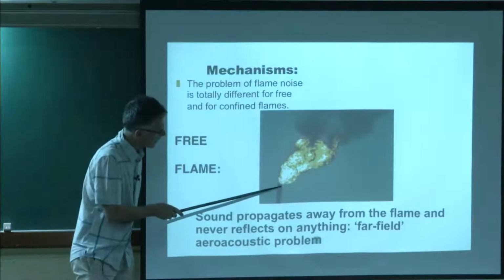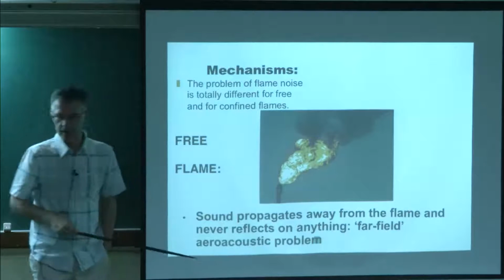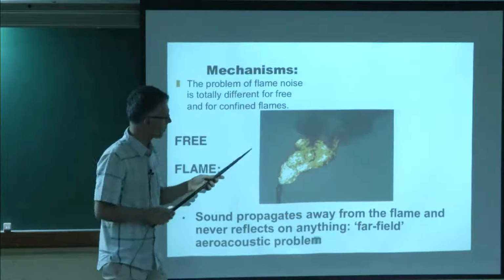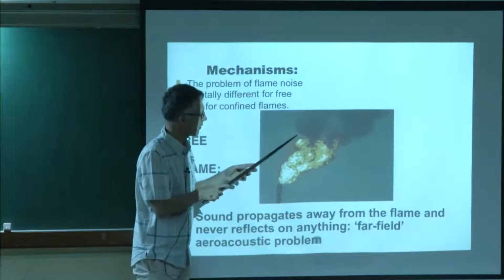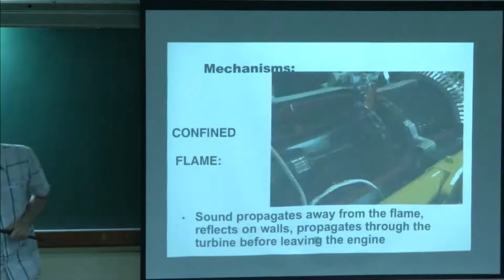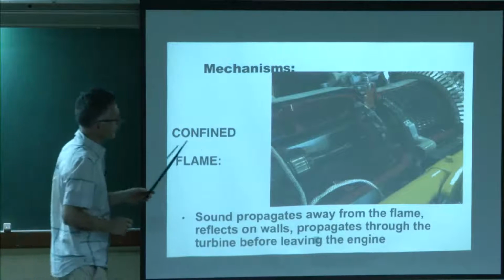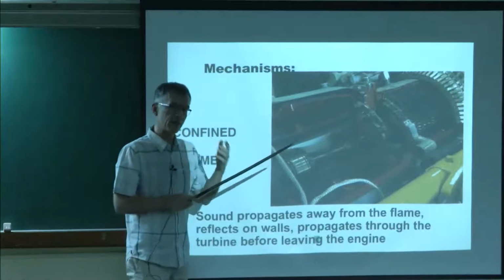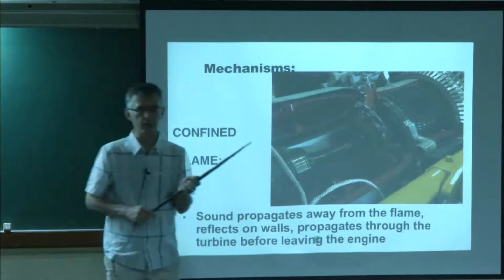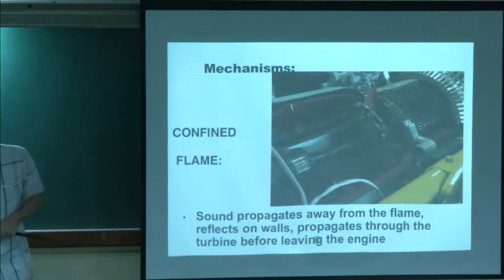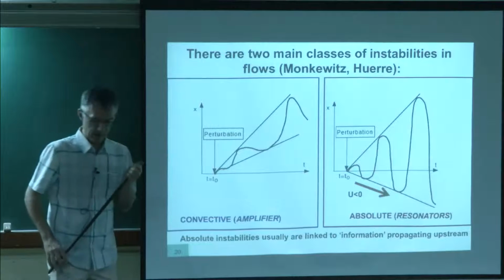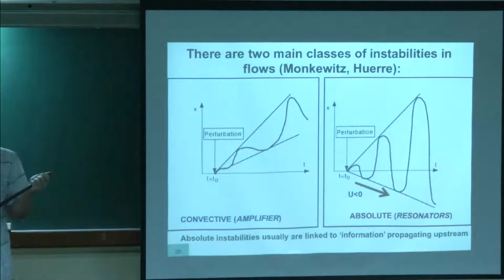So if you have a flame like this one, blowing and burning in free atmosphere, that's a relatively simple aeroacoustics problem because this is a source of sound and it radiates to the far field and it makes noise. But if the flame is confined now, the noise is not able to leave, and that's where things begin to be dangerous, because if this noise comes back to the flame itself and modifies it, then we can have a combustion instability.